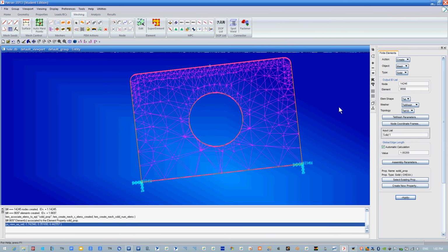As you can see, because of our mesh seeds, you have more elements near the top of the structure and more elements around whatever surface or feature we're trying to include in our elements, say like a through hole. You've got that there. And at the base, there's not very many. In this case, that's fine because we really don't care about the base all that much. There's really not much to it there.